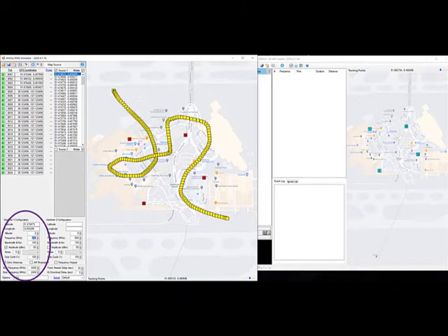Drone parameters are set here: frequency and bandwidth of the drone. Typically the bandwidth is 10 or 20 megahertz, but you can set up whatever you like. Amplitude we'll leave as is. The check mark there lets you turn the power on and off. You can also add noise to the signal. There's both square noise and Gaussian, and you can set different levels of that noise.